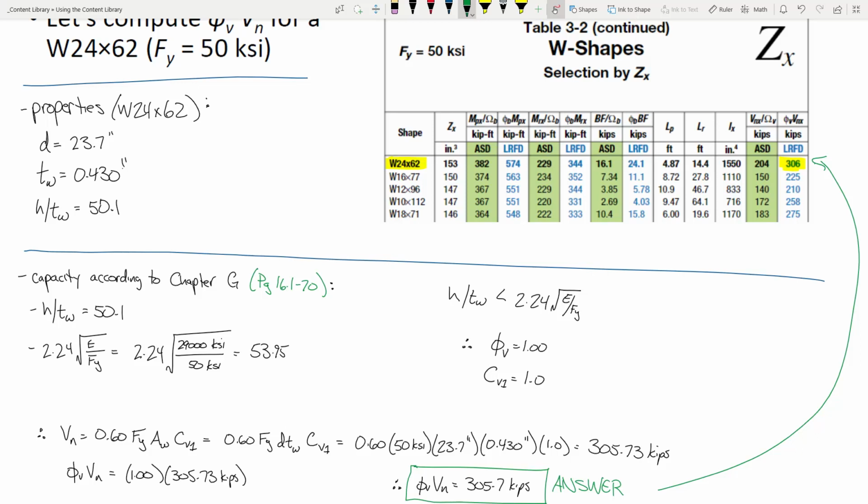And what happens is, this steel over here is useless. It's all buckled. But in here, you can actually keep resisting load, and it develops this sort of field that resists the load in tension, because this is the segment that's being yanked on. And steel loves to be in tension. So you can actually develop what's called tension field action. That's what that TFA stands for.